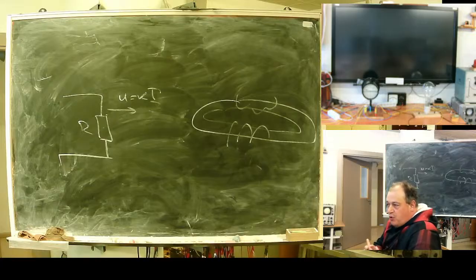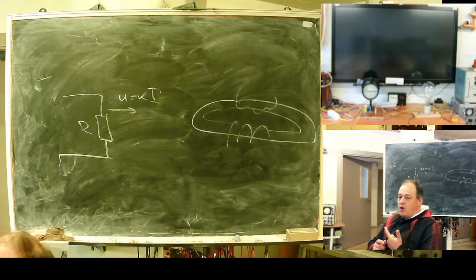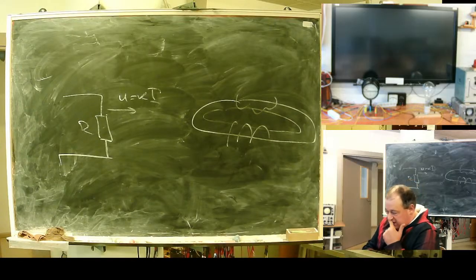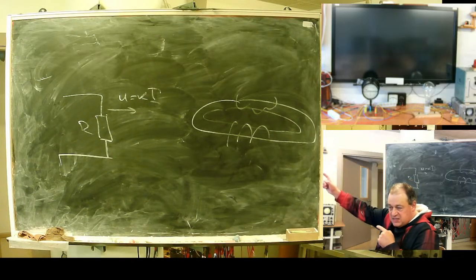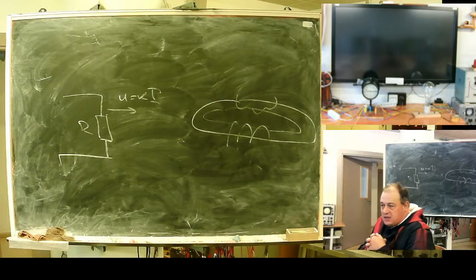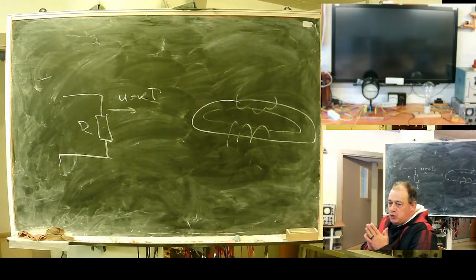Very serious problem: photovoltaics, 600, 1000 volts, up to 2000 volts. They are with small currents, but photovoltaic modules connected in series operate at quite high voltages.